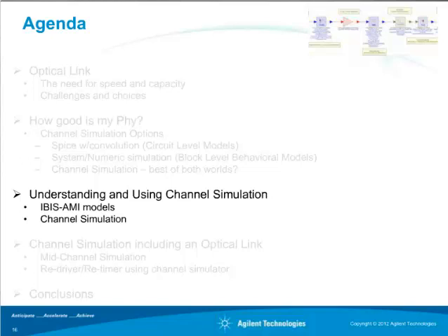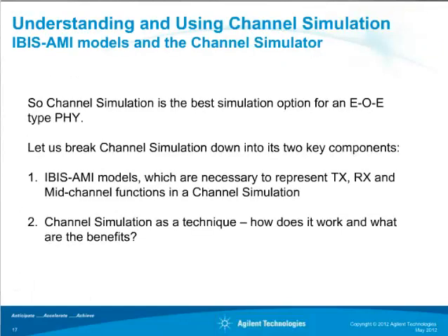So let's dive a little bit deeper into using channel simulation, and this really does break down into two parts. Given that channel simulation is a very good option for E-O-E type PHY, let's break it down into two components so we can get a handle on it. The first is those IBIS AMI models that are used to model transmit and receive, and also mid-channel functions, which we'll come to in a bit. And then we can also look at channel simulation as a technique, and we'll do that in the coming slides.